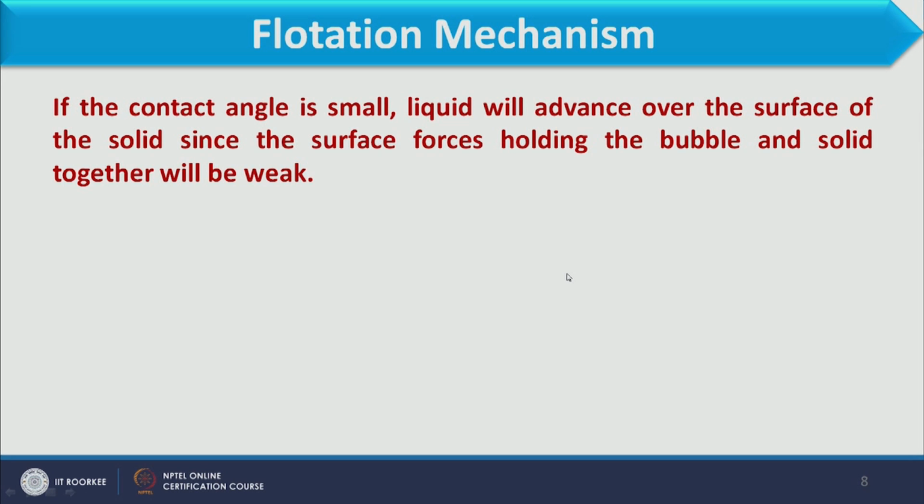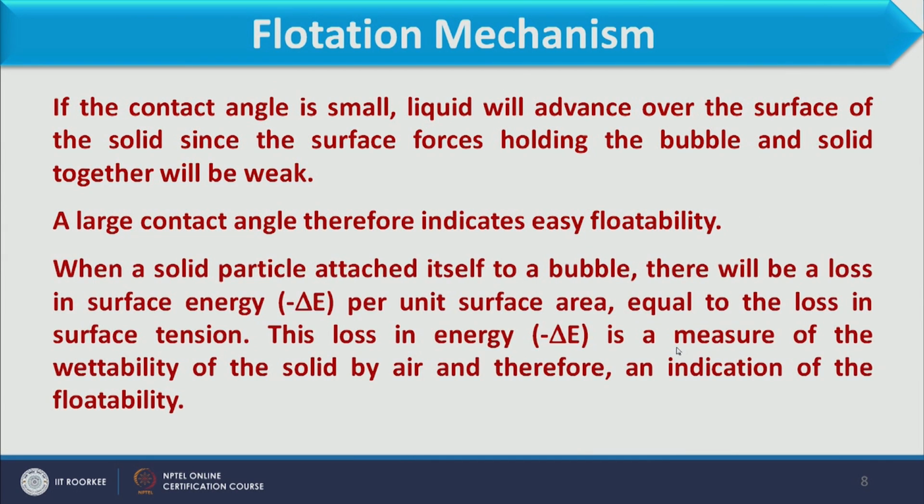When the contact angle is lesser, after some vigorous agitation, the bubble can be separated from the solid and liquid will enter between solid and bubble. So, it will reduce the wettability. If we want a compound to be floated, the contact angle should be large, and this contact angle is between the air bubble and the solid. So, a large contact angle therefore indicates easy floatability, as we have just discussed.